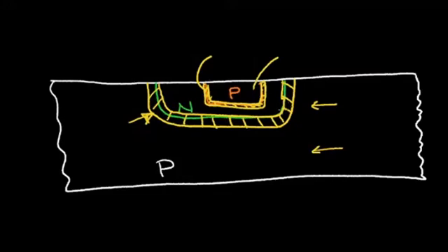lower junction. And also, I can infer something about breakdown voltage. This depletion region here is wider, so it will have a higher breakdown voltage. In this top region, this junction, this depletion region is narrower, and it will have a lower breakdown voltage.